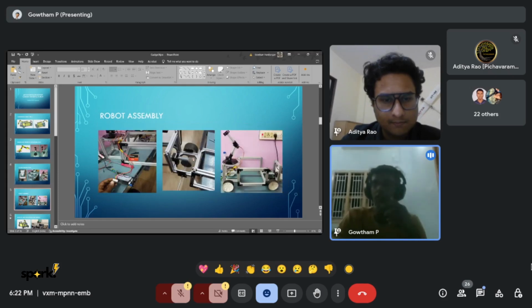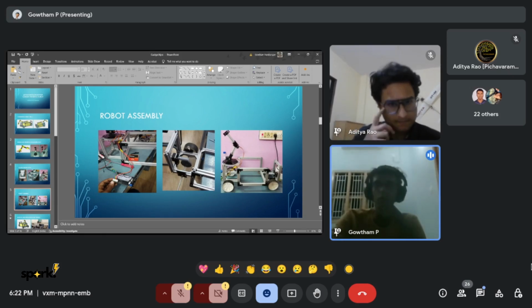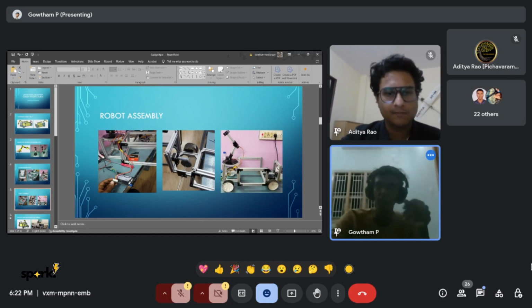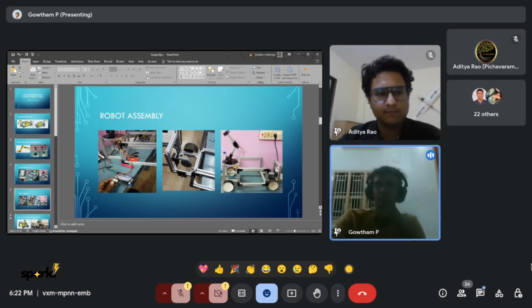As I said earlier, initially I wanted to go for mecanum wheels and geared DC motors. But for uneven surfaces such as rooftop terraces, there's usually a lot of wear in the mecanum wheels as well as the gears in the DC motors. So I went for normal wheels as well as stepper motors for the rear axle.